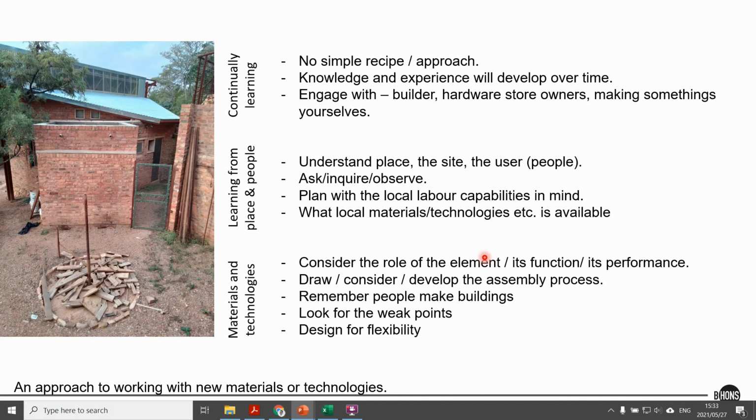Windowsills shed water, but they also define the opening, and can also be considered a structural entity, as if you include the lintel at the top. What is that part that you're busy with, and what must it really achieve? Sometimes it's one function, and sometimes it's multiple. But if you understand what it must do, it's already easier to understand the next thing, the weak points of it. Look for those weak points. Look for those points where you think, okay, wait a minute, that's not going to work.